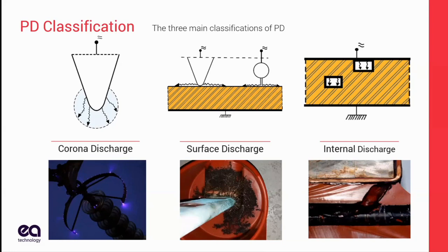That carbonized track is conductive. And because it's conductive, the voltage appears at the outer edges of those branches. So now we have voltage where we didn't think we should, where we wouldn't have it by design. So we're more likely to encounter arc flash when things move. That's another side effect of partial discharge we need to be careful of.